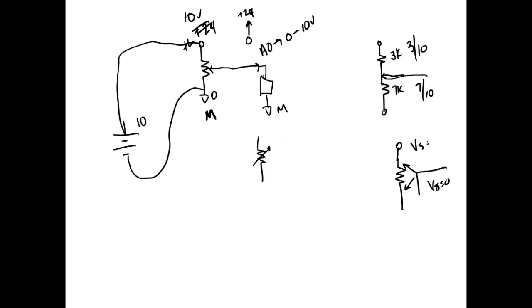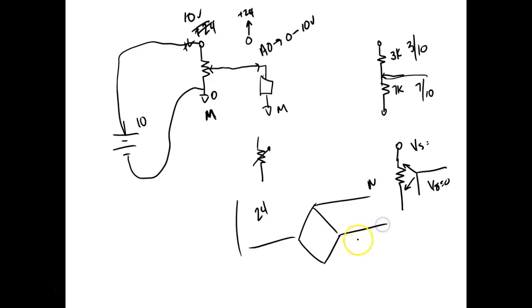Now, normally these analog sensors that we have available to us will power up off of 24 volts, and then this would be an M. But when they output, it's from 0 to 10 volts. So they have the voltage converter inside the sensor. Does that make sense? And so 0 to 10 volts is pretty common for analog in the processing world. It's just like 24 is a standard power supply that we use for our PLCs.